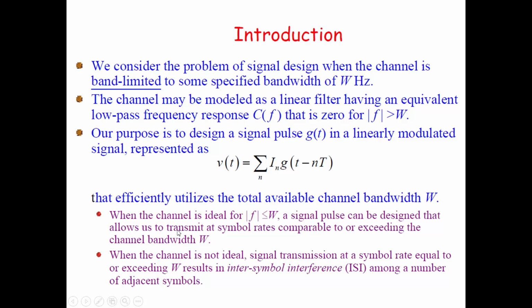Now, what exactly is intersymbol interference? Intersymbol interference is the spilling over effect of the previous symbols onto the present symbol. Since the channel is not ideal, there is a spillover effect of the previous symbols onto the present symbol, which leads to interference in the detection of the present symbol. So you may make a wrong decision as to whether it's a zero or a one.